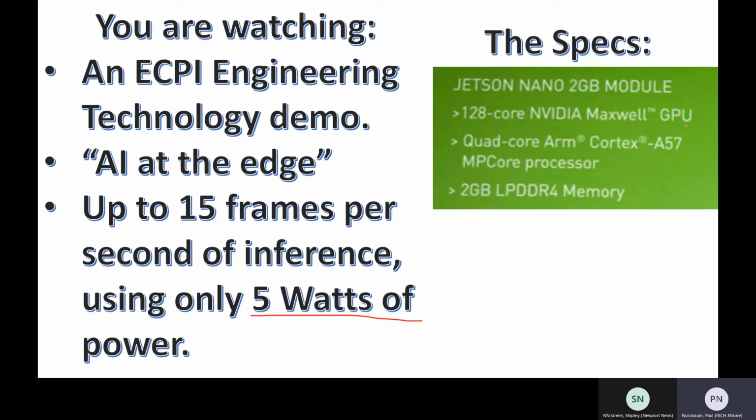So having things done in parallel, unlike your Intel CPU that can really only do 4 mathematical operations all at once with its 4 CPU cores, being able to do 128 of them is very important. On top of that, it's included a CPU. So there is a 4-core CPU similar to the one you have in your PC, and that manages feeding this beast, if you will, feeding it with the pictures it needs, and going ahead and outputting, and also providing a user interface, a Windows user interface, running the Linux operating system, I think it's Ubuntu in the case of the one you just saw.